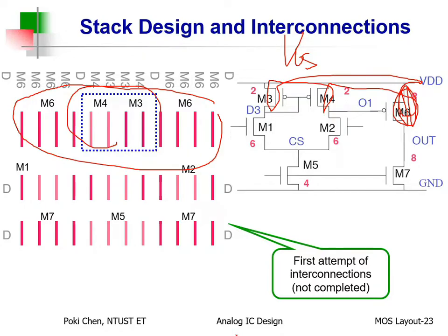Dummy means what? It is not functional for the real circuit. That is, you need to shut it up. In the past, dummy for what? To protect the main device during fabrication, right? But now, dummy is not for that kind of purpose. Dummy is for you to stack all of them at the same time to achieve other good purposes, just like common centroid, blah, blah, blah. Okay? And more likely also reduce the overall area. Maybe. Okay, and forget about it.